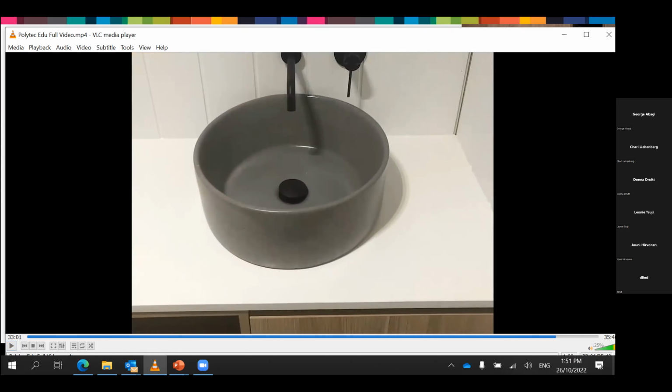Just on that point there, with taller cubicles, we always try and advise to do the ambulant toilet in the corner. But the reason for that is we can't tell what the installers are going to be using to secure the partition division to the back wall with. So there's a lot of hardware suppliers out in the marketplace, and there's some fantastic products out there, and you might specify the right equipment to use, but we don't know what the installer is going to be using.